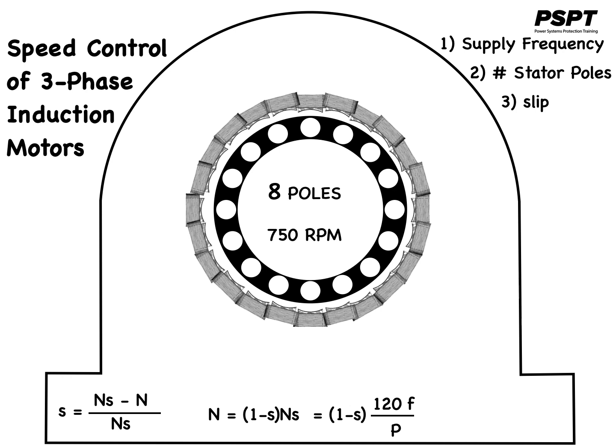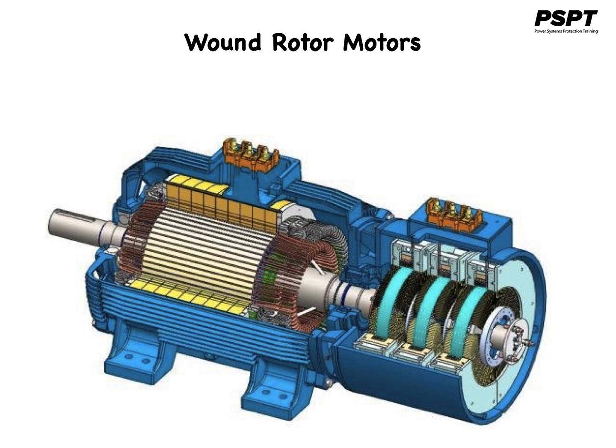4-speed motors are sometimes equipped with 2 separate stator windings, each of which provides 2 speeds. The disadvantages of this method are that it is not possible to attain gradual or continuous speed control. Speed control is in steps. And because of the complications in the design and switching of the interconnections of the stator windings, this method can provide a maximum of 4 different synchronous speeds for one motor.